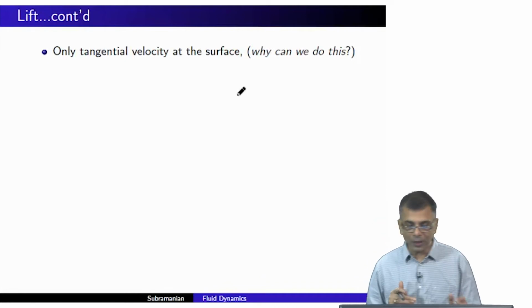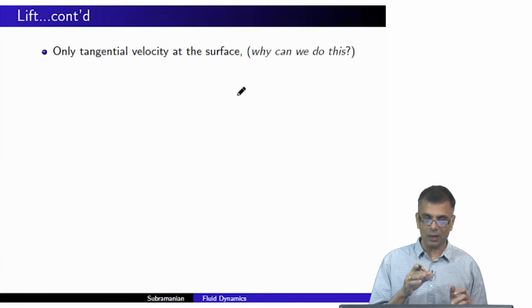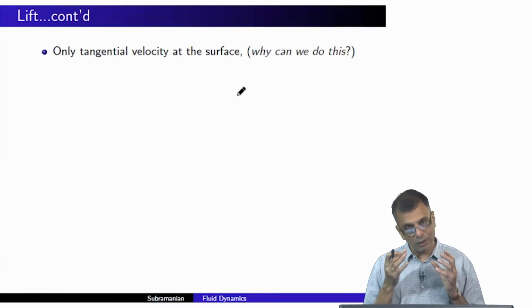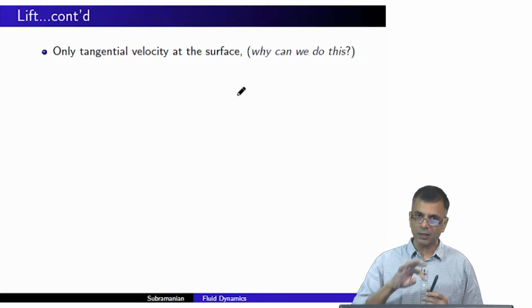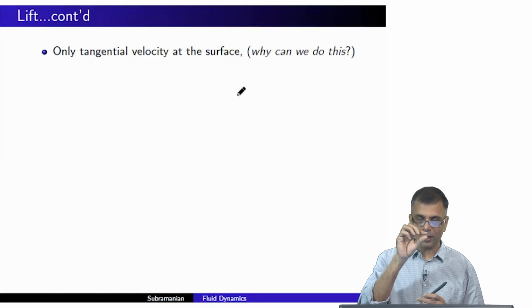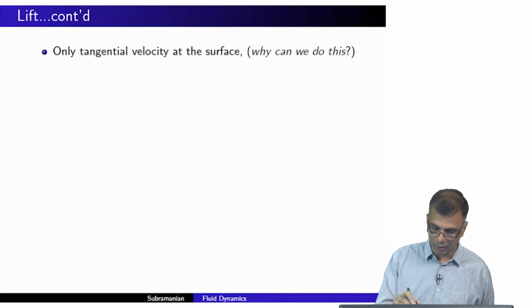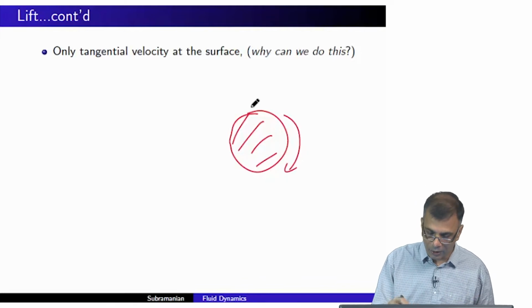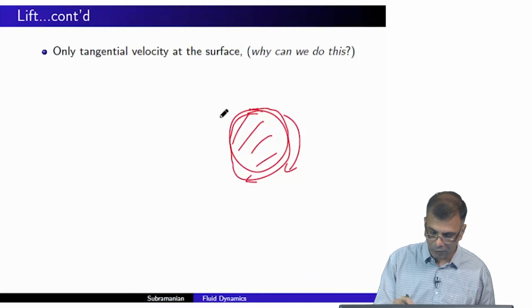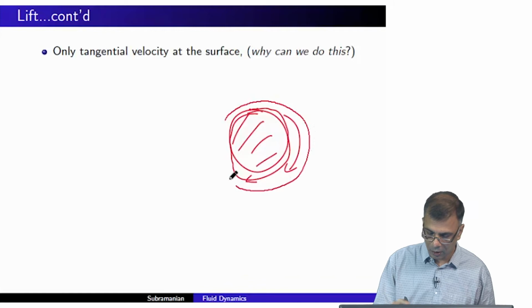So what's happening is the ball is actually spinning in the clockwise direction, and in a real world situation, there is finite viscosity, and as a result of the spinning, the fluid layers that are closest to the ball are actually being dragged along with it. So this would be the ball, and it's spinning like this. My drawing's not very good, like this.